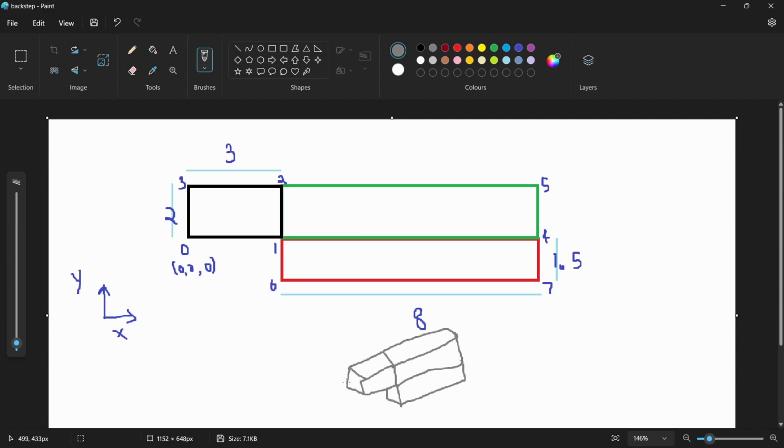Okay, now the back face is what we made, the face here. Now we want to make this one. So this is our 0th point, this is our 3rd point, and this is our 5th point for reference. We are making an exact copy of these, just incrementing the z-axis. We're going to increase the value of z and create new vertices some distance from the backplane.